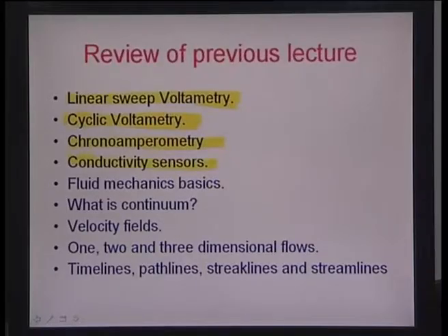So, we also talked about conductivity sensors. Conductivity essentially means the inverse of resistivity, and the increase or decrease in ions of a particular species would definitely lead to the increase or decrease in the conductivity, and you can use this measurement technique by assembling together what you know as a Wheatstone bridge.